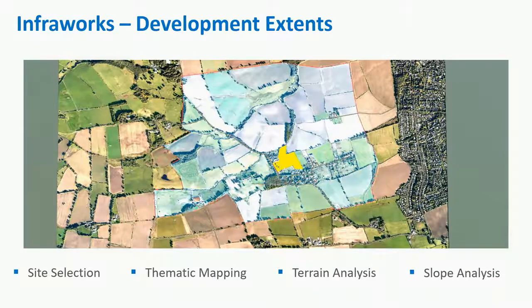So we're going to go through, and as I said before, we've got a set of constraints for local authority buildings, so density controls, land use areas. I'm going to show you how we can extract that information and bring it into InfraWorks, apply what we call tags or asset IDs, get them to show within the InfraWorks model itself, get them to color up by sending some rules through, and then we can also link to external documents, external websites, and the like. So we can build within the InfraWorks model itself a very detailed narrative of what's happening in and around the site and why we've made such design decisions.